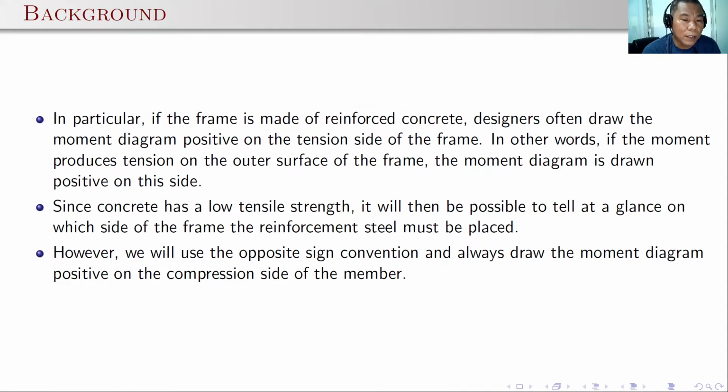Also, since concrete has a low tensile strength, it will then be possible to tell at a glance on which side of the frame the reinforcement steel must be placed, because we know at the tension side the concrete will crack, so we need to put the reinforcement there.